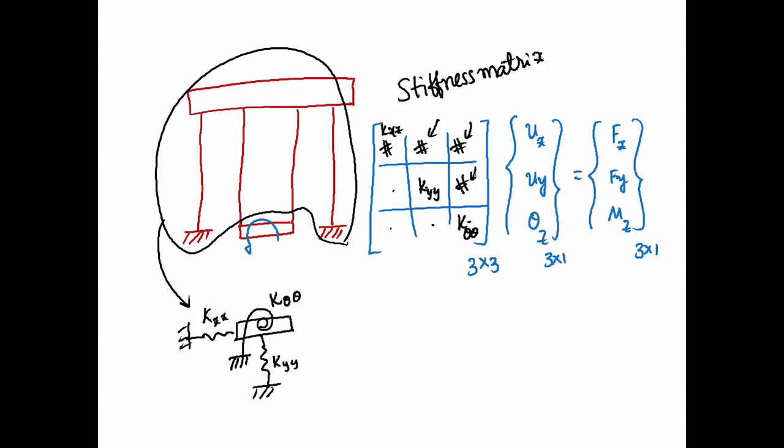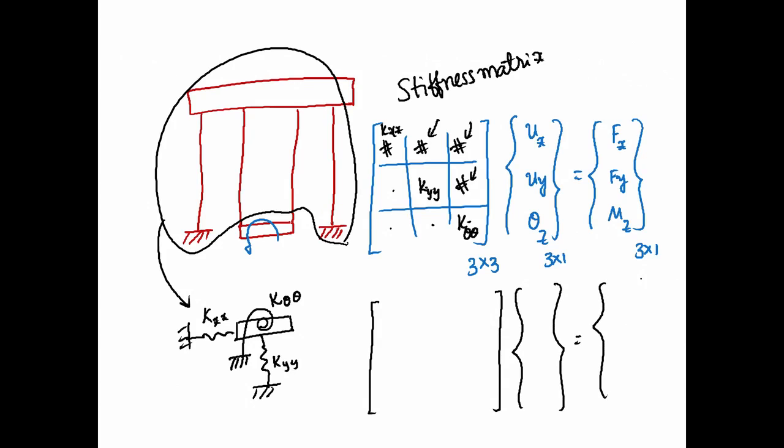The way we will do it is to construct what we call the compliance matrix, which is the inverse of this, meaning it will relate to the inverse of the stiffness matrix. Now, this is the stiffness matrix, this one is called the compliance matrix.